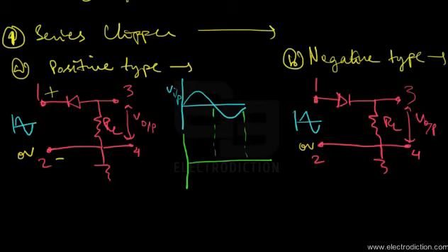Now when the second half cycle arrives, the polarity across terminal 1 is reversed and it becomes negative compared to terminal 2, which goes to a positive polarity. At this time the cathode of the diode has a negative voltage, and so it begins to conduct current.